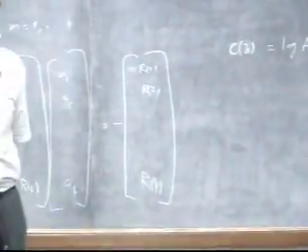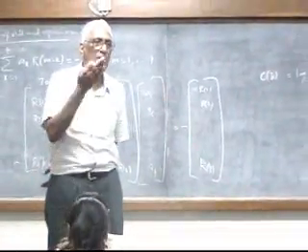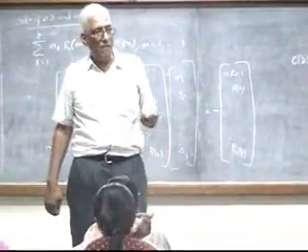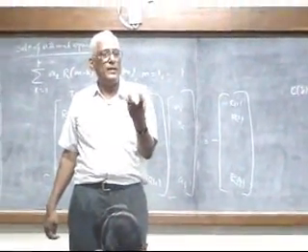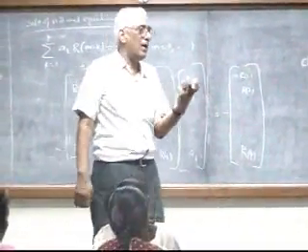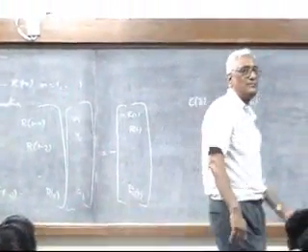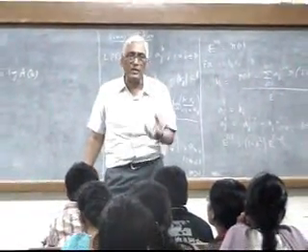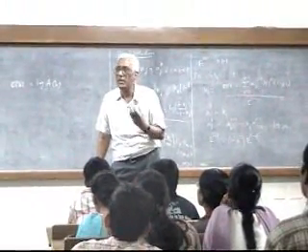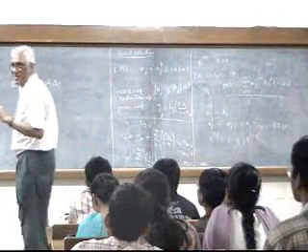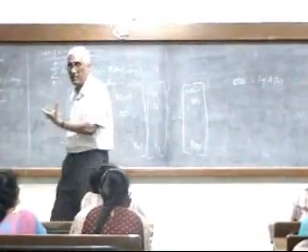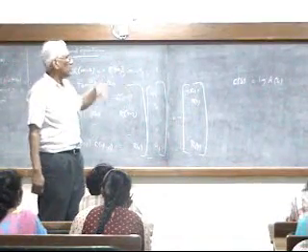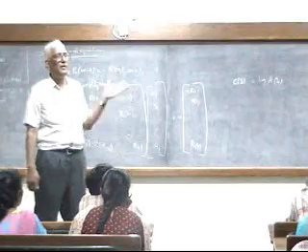So why do you need all of this? For example, from a coding point of view, I need log area ratios. A lot of people examined all these and asked which one is effective when I have to represent it in a finite word length without spoiling the characteristic. That is what they have studied. From the quantization point of view, area coefficients are supposed to vary. Whereas if you want to match two spectra, from the matching point of view, the most effective one is the linear filter cepstral coefficients.